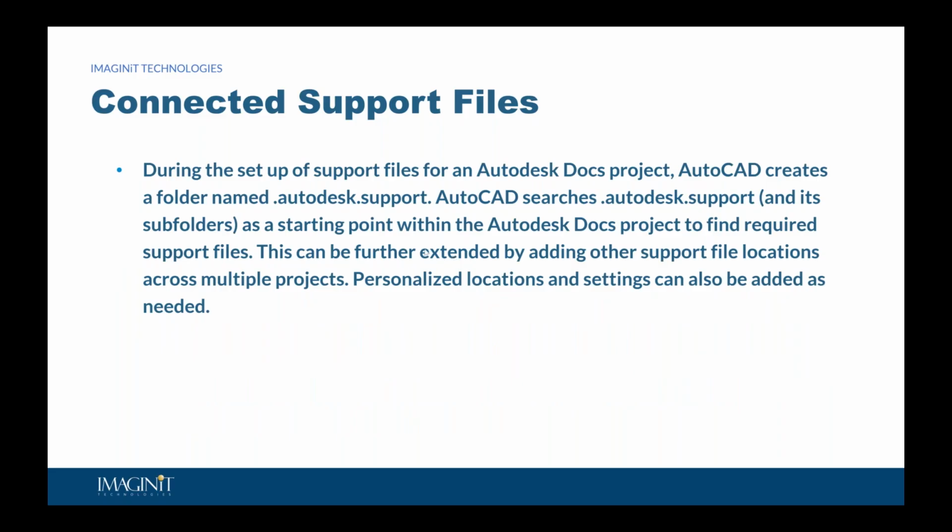So during the setup of these support files for an Autodesk Docs project, AutoCAD creates a folder named .autodesk.support. AutoCAD searches that support folder and all of its subfolders. And this can be further extended by adding other support file locations across multiple projects. Personalized locations and settings can also be added as needed.